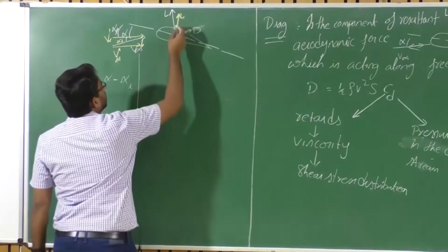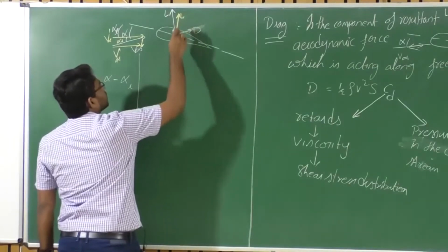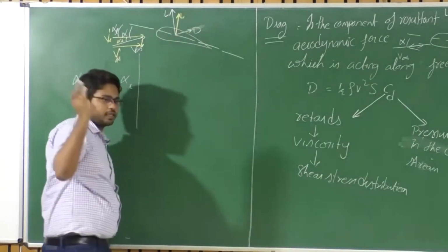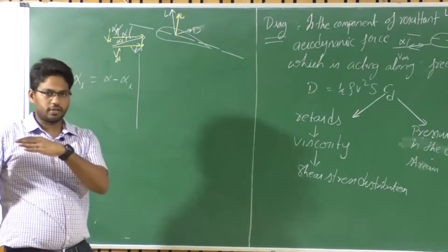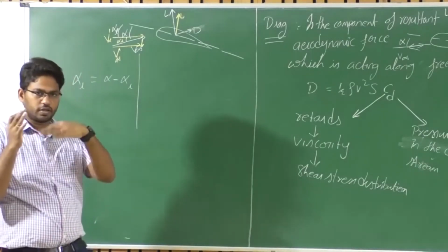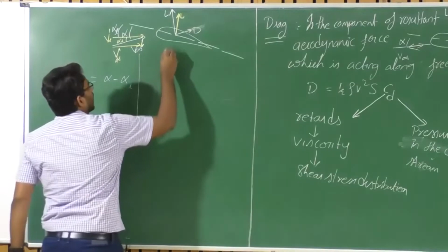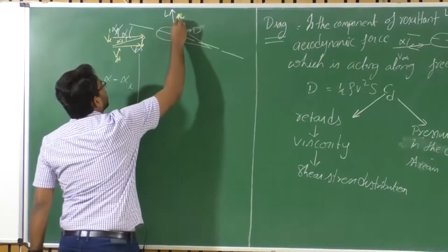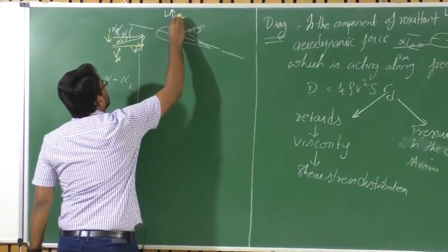A component of this lift that is generated at that particular location, because of the induced angle of attack, acts in the direction of drag, right?